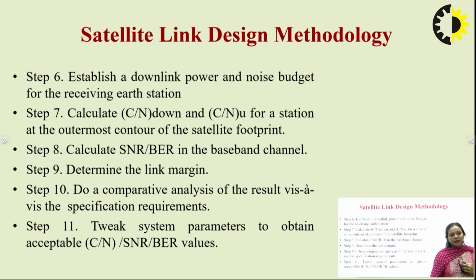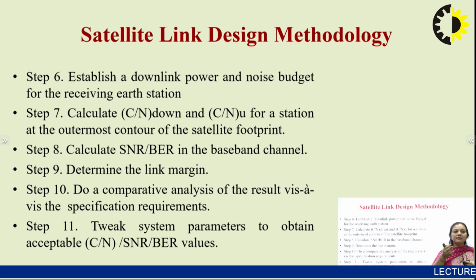Then establish a downlink power and noise budget. So this was for the first step. First 1 to 5 steps we have generally considered from the earth station to the satellite. Now we are considering the downlink, that is from the satellite to the earth station. So establish a downlink power and noise budget for the receiving earth station.